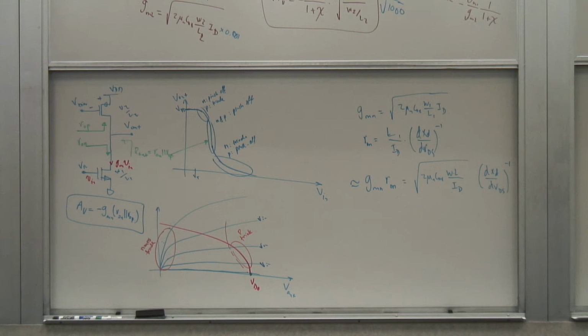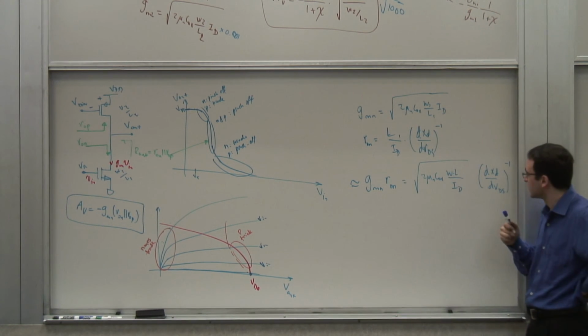The width part is kind of clear, right? Because you increase the width of the device, you have more transconductance. If you double the width, it's like having two transistors in parallel, driving the same node. So that helps. But the transconductance is only dependent on the square root. That's why there's a square root dependence.